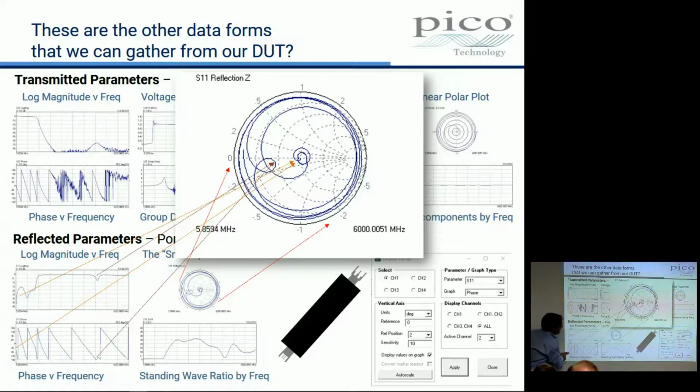And phase increases. So again, look, as we go up in frequency, we go around like this. And then as we come to this point, as we come to the roll-off, look, the reflection starts to get bigger in magnitude. It's still sliding around in phase. So here it is, it spirals out, and it comes to the circle of mismatch. So it started at the point of match, and it spiraled out to the circle of total mismatch. Yeah? And we'll see more about that next time. So that's how those two plots relate to that.